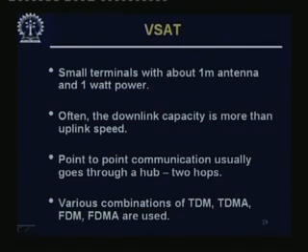So, you get considerable delay now of the order of half a second for this communication between A and B. But then there is no setup time. So, you can set it up very quickly any way you like. Various combinations of TDM, TDMA, FDM and FDMA are used for handling the MAC, and this is all controlled by that central hub. So, that is how it is done.